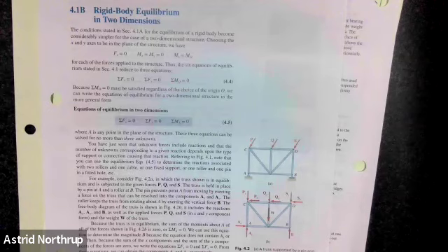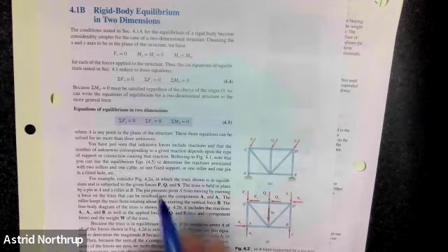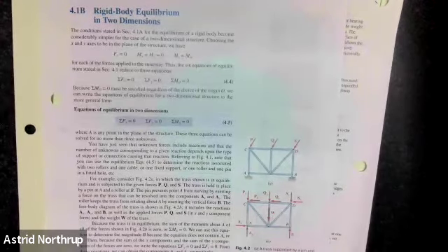I have some pictures, they're on my mechanics materials page, but the Willwood Bridge, which is southwest of here, is a really good picture because there are expansion joints in it. So it's not just at the end where all of that is taken up, but there are, I like to think of them as cracks in the sidewalk, where it's a little bit more complicated than that, but that allows sections of bridge to expand and contract. And that's also another reason why there are cracks in a sidewalk, so that the concrete can expand and contract a little bit, mostly with weather, a little bit with load, but mostly with weather.